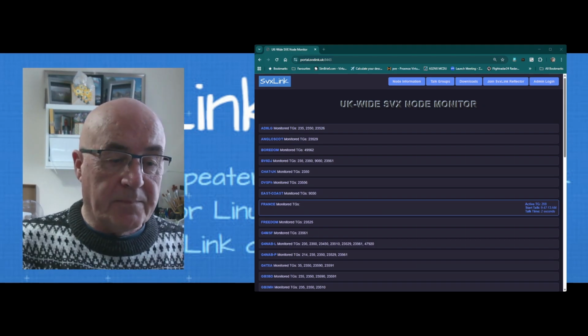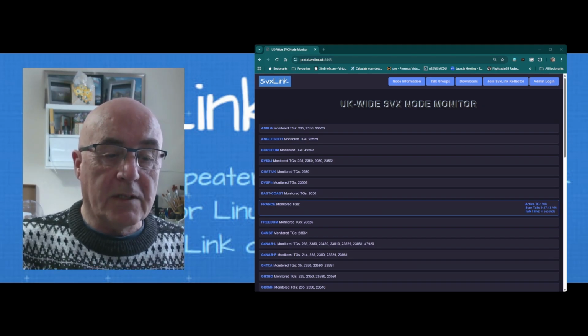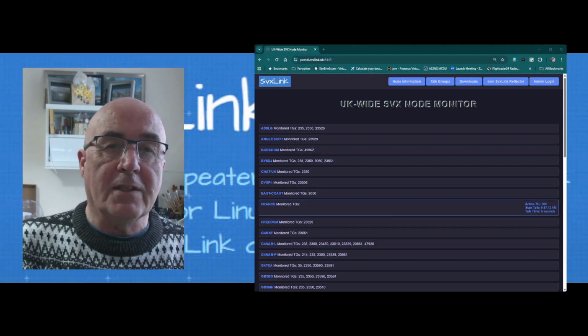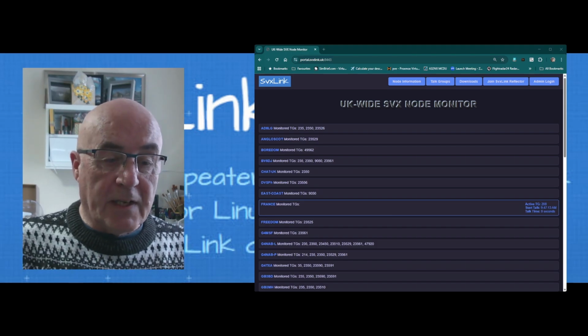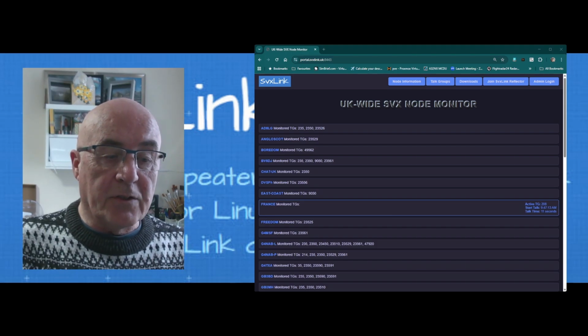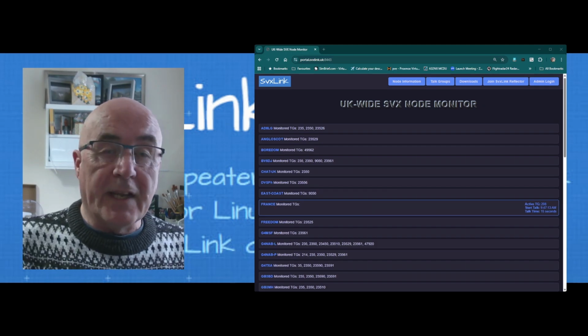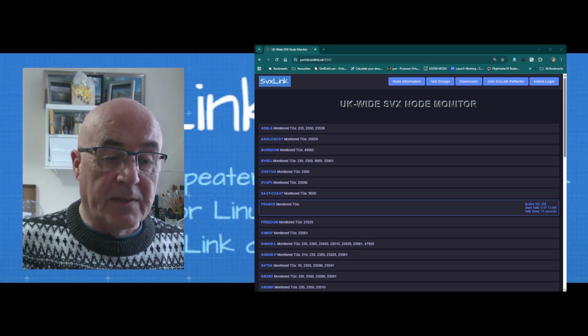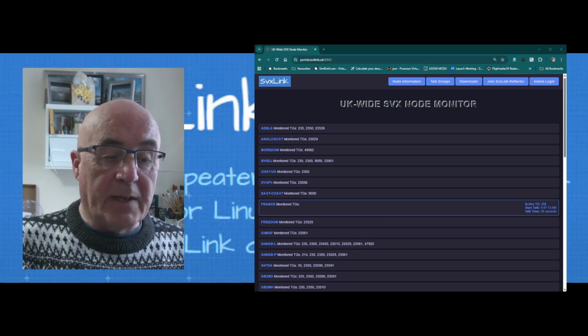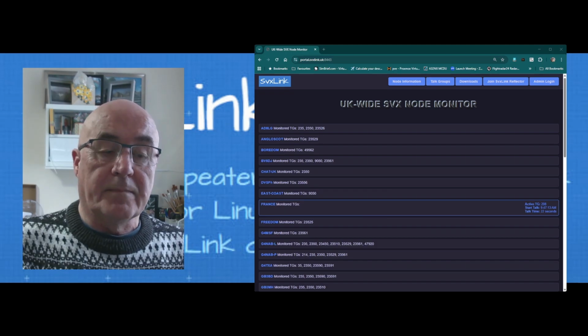Now, stage one. Provided the system operator of a repeater has configured his reflector logic in the SvxLink configuration correctly with an authorized key, or as of now an X509 certificate, the repeater has a passive connection to the reflector.